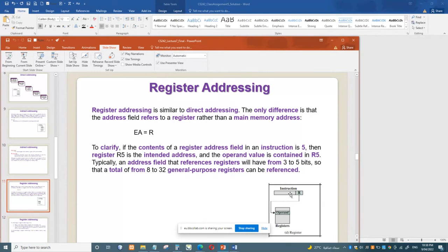Because you know that like MIPS, we have 32 registers. Every register has a different number, though we call them by their names, V0, A0, T0, S0, they all have a number, starting from number 0 to number 31. So every register has its number. So in case of register addressing, in the instruction, we don't give the register name actually; rather we provide the number of the register where the register contains your operand.